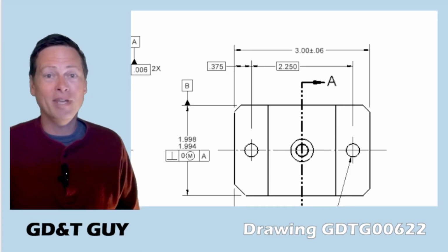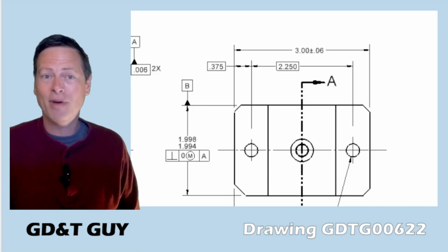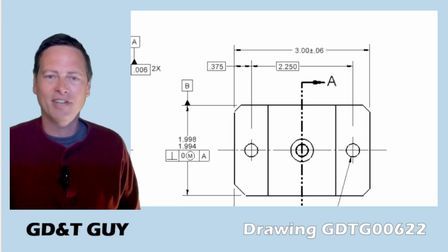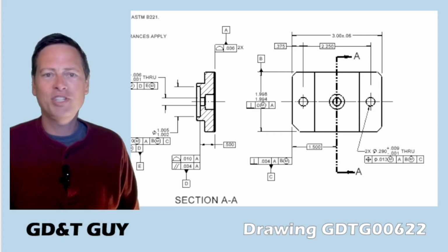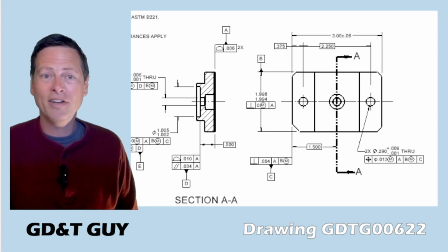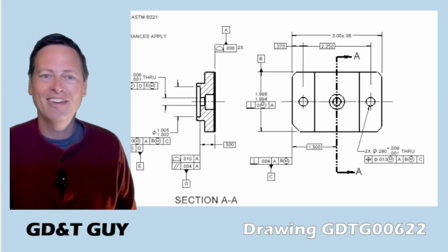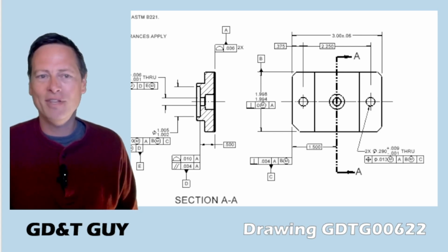And maybe we could beat this simply by cutting that plus or minus 60 thousandths tolerance in half, but that's always regrettable when we have to tighten a tolerance. Or I guess we could change the design to make the part wider or the spacing of the holes narrower, if we're able to do that. Maybe there's a reason we're stuck with these dimensions.